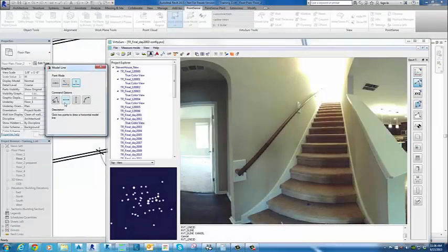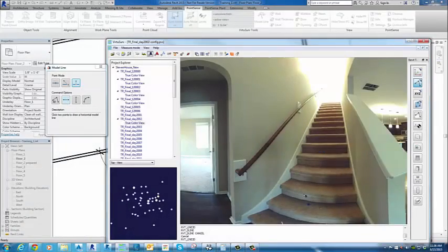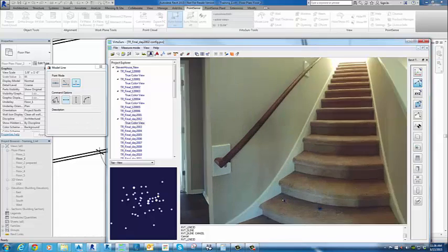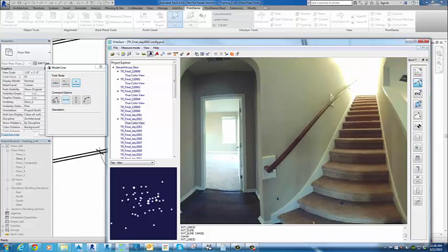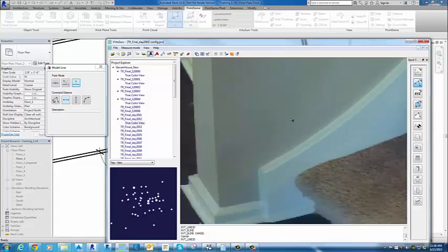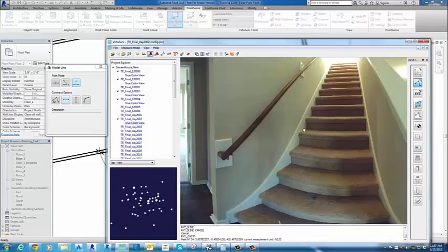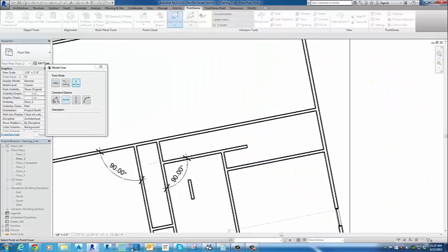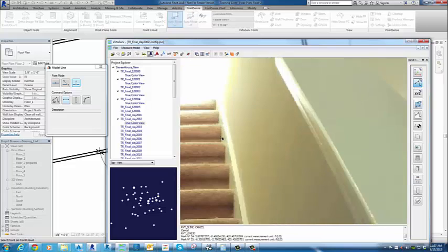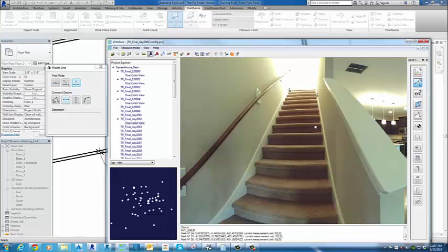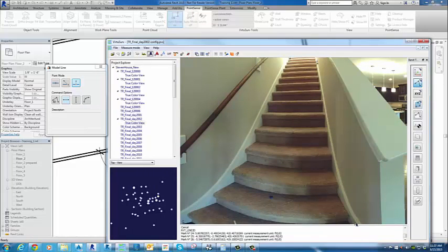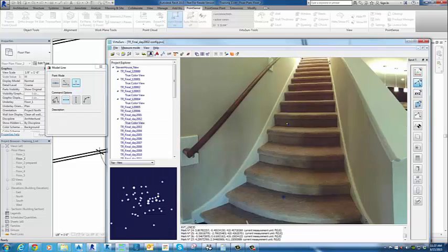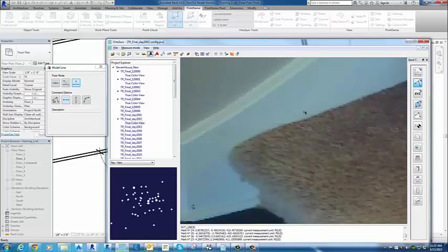Creating stairs and irregular objects, you have the option to just lay out modeling lines. In this case, we're going to lay out horizontal modeling lines for the boundary of the stairs and for the risers. And to do that, it's really simple. I find it much easier to click in the high-res image view in VirtuServe to send our line work over to Revit. So first I'm just kind of placing some boundary lines here,